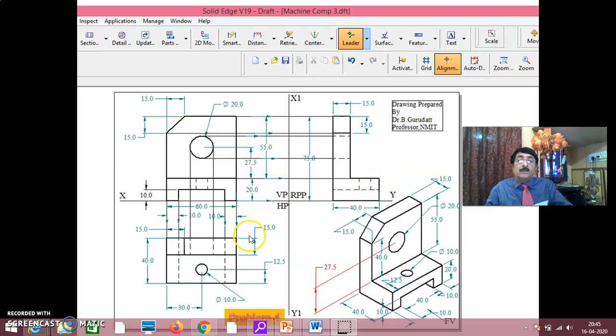And when you are looking from here, you can see this edge. That is what I have darkened here. And when you are looking from here, this fold cannot be seen. I have made this dark dotted. And again, when you are looking from here, even this fold cannot be seen. This fold you show dark dotted here also, in the side view. That means at a distance of 12.5, as you know very well, you take one dotted line here to a distance of 5 mm. In that way you show. In that way we come to the end of session 6.